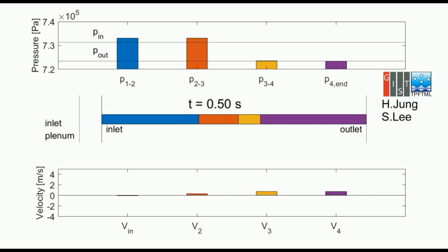However, the high flow resistance of the yellow-colored high-density wave front causes liquid and vapor to flow back towards the inlet. This backflow persists until the high-density wave front is discharged at the channel outlet, overcoming the resistance. The vapor and liquid refrigerant that flow back to the inlet are then reintroduced, forming a period.